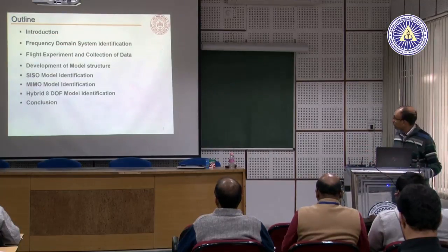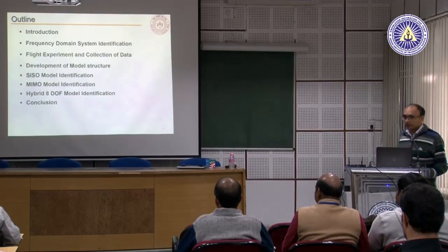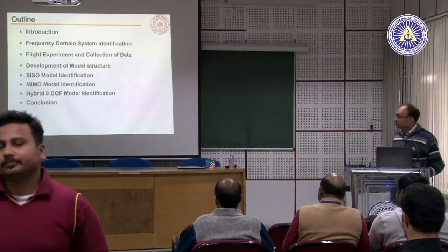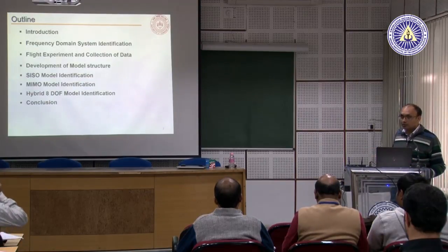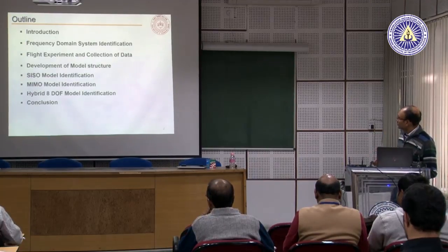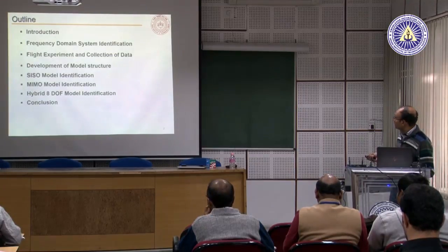Okay. So, this is the outline of my presentation. I will start with the introduction, then we are following an approach called frequency domain system identification. Now, you can also carry out time domain based system identification. To apply these methods, you need not resort to sophisticated software. Some of the basic tools are available in MATLAB itself. MATLAB has a system identification toolbox which can be employed to identify models in real time, using mostly time domain based methods. Probably they have frequency domain based methods as well, but I have not seen.